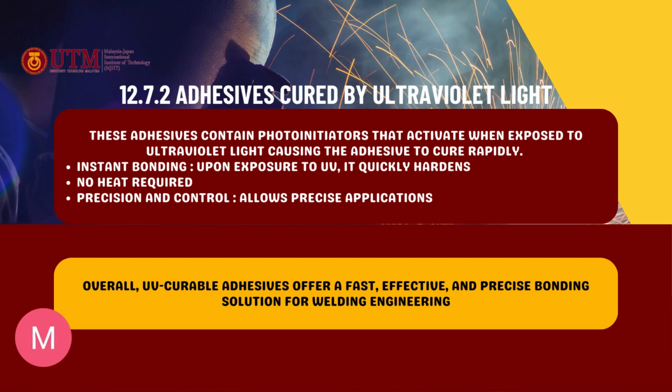Next, adhesive cured by ultraviolet light. This adhesive contains photoinitiators that activate when exposed to ultraviolet light, causing the adhesive to cure rapidly. Instant bonding, no heat required, and precision and control. So overall, UV cured adhesive offers a fast, effective, and precise bonding solution for welding engineering.